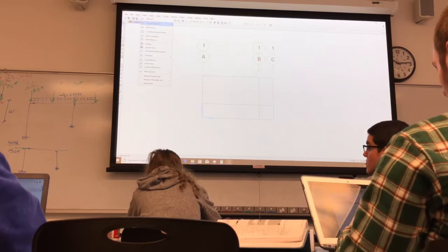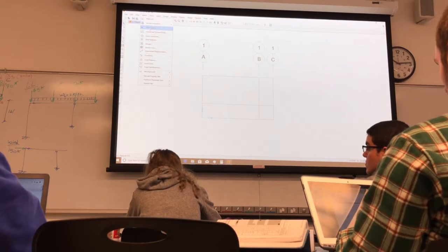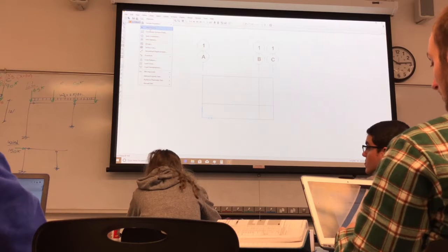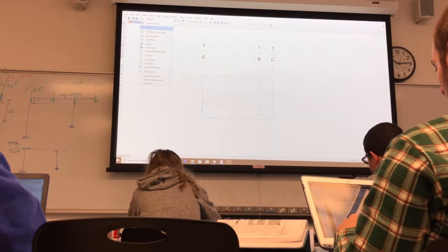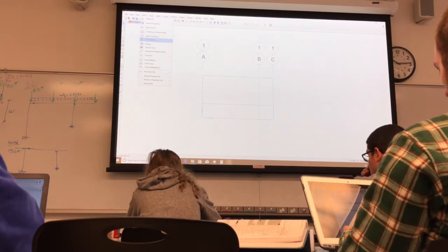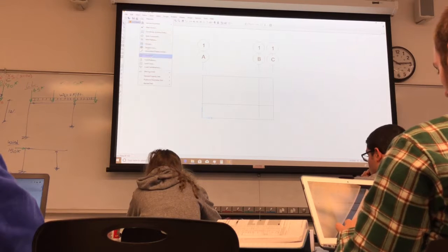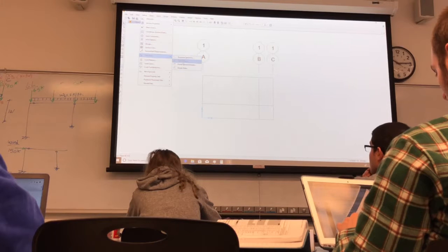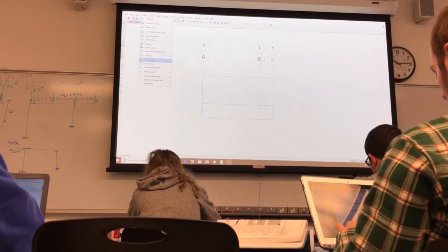Now I don't need a mass source. We need masses when we do dynamic analysis, because you're defining mass when you have ground motions. Here we're doing earthquake as a point load, as a static load, so we're not doing dynamic, so we don't care about the mass. We don't care about joint constraints or all this stuff. We don't have functions, we're not doing dynamic analysis. So what we care about is loads. We want to assign loads.